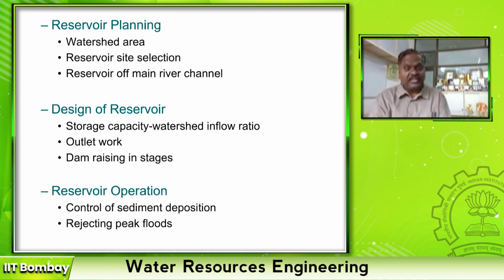Then while designing the reservoir, depending upon the measured sediment for a certain period, provide the appropriate area or volume for the sediment deposition. Then design an appropriate outlet such that the sediments get flushed off. A very recent technique for outlet work is the orifice spillway type.